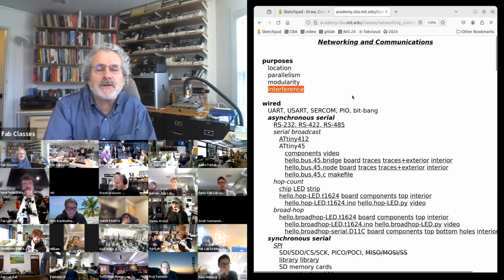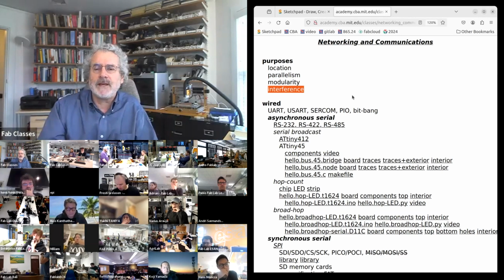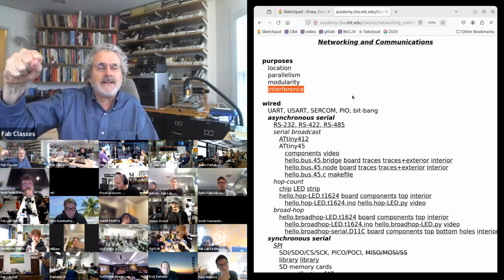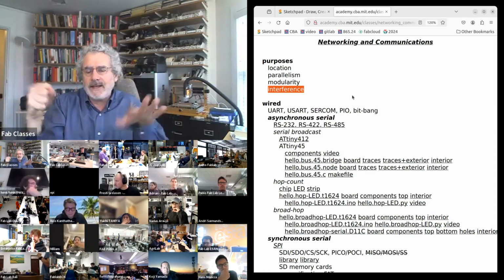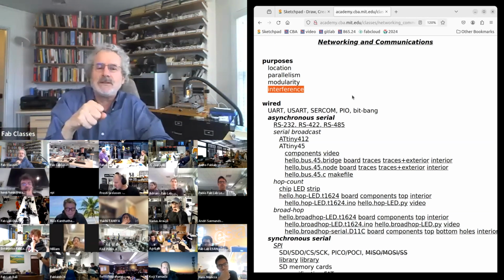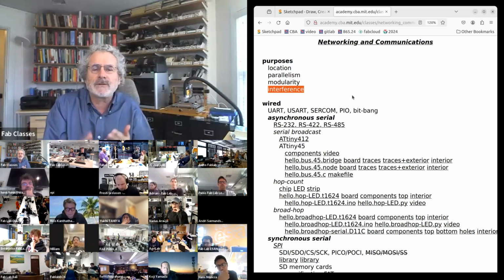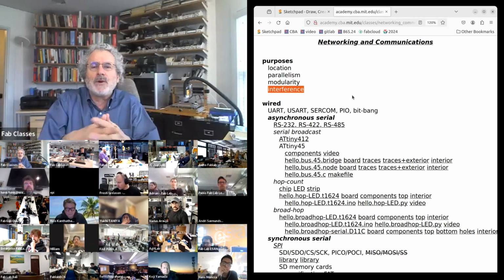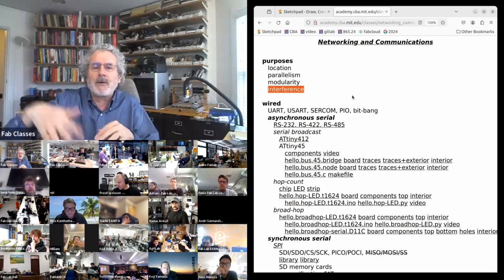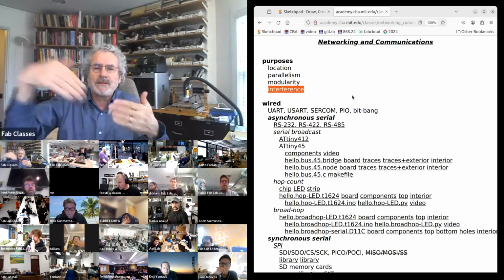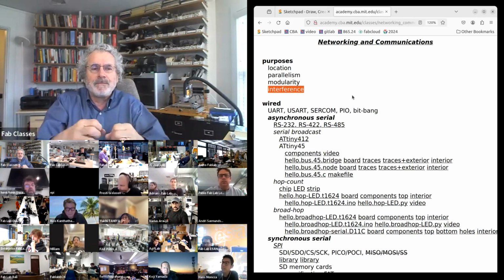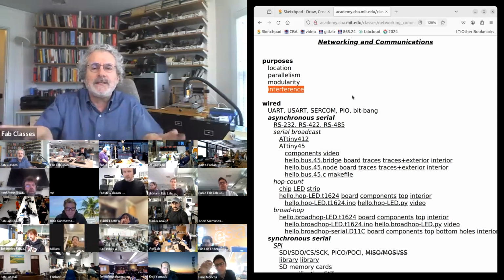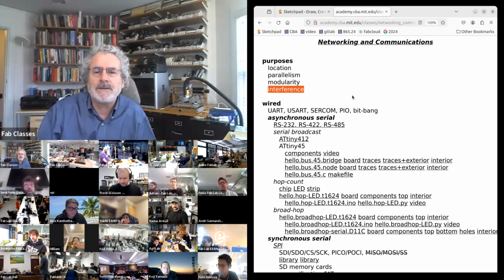And then one is interference. For a system where you, for example, have motors that are high voltage, high current, and then you have, say, microphones that need to listen to noise with very little electrical interference. If you put them all on one circuit board, you have to work hard to prevent power supply ripples from the motors getting into the microphone. But if you pull them apart in separate systems, you can decouple the powering much more cleanly.